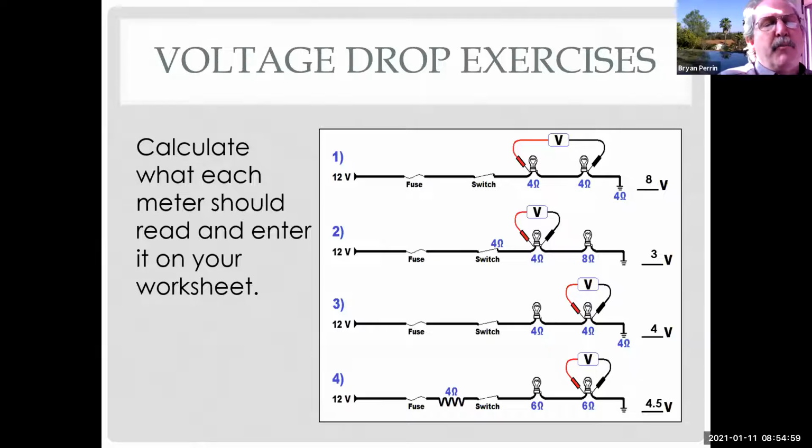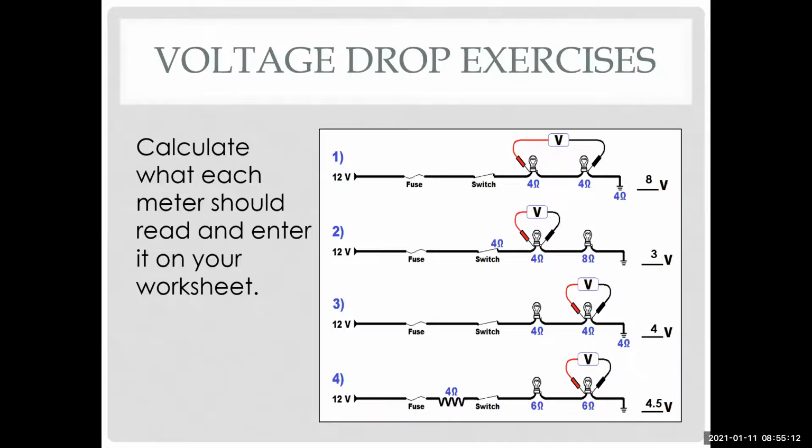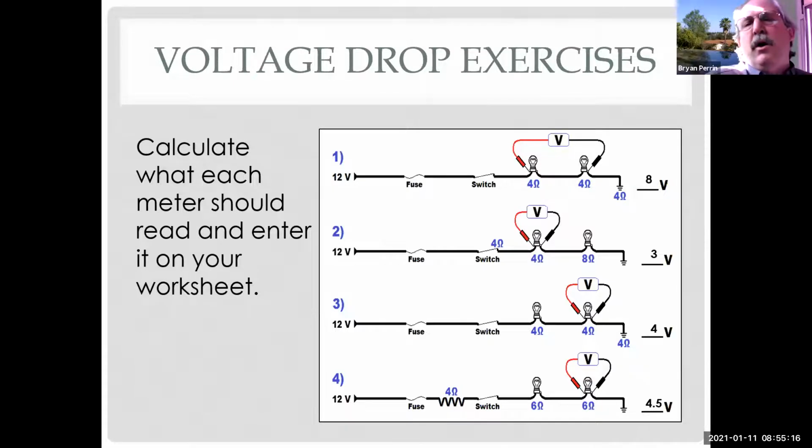And the newer power probes will actually give you a voltage reading on the display. What they used to do in the old days is they'd use a test light because it created a parallel circuit. And the test light puts a load on it. So if the test light didn't light up, that meant I didn't have good potential there.